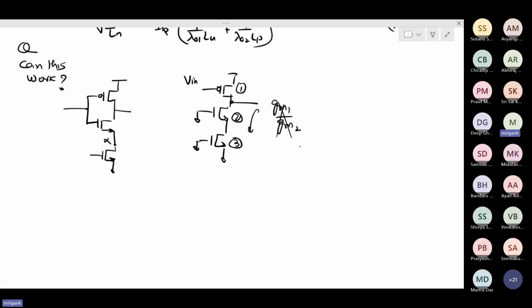And the second thing is, even if you get some small signal gain from here, if you have this circuit, here you have the impedance as GM2 RO2 times RO3. Looking downward, it is a stack cascode device. This derivation we have done earlier. If you don't remember, we will try to address it later.